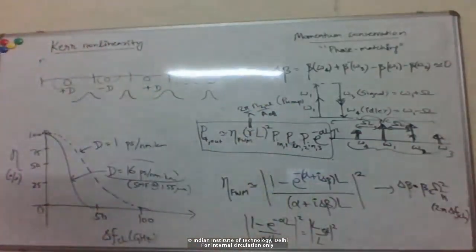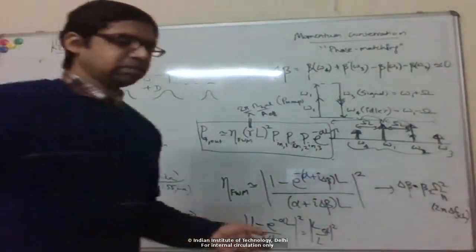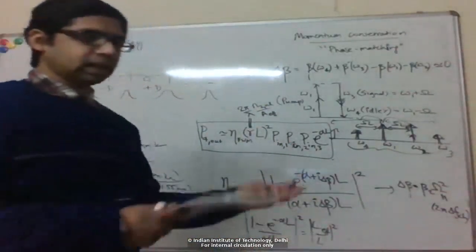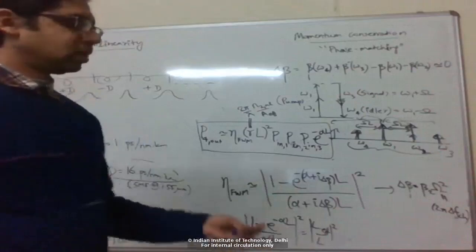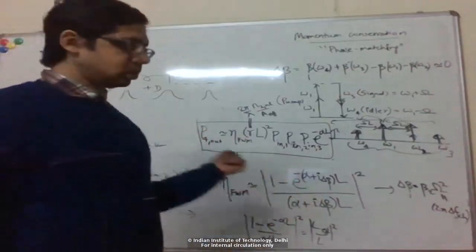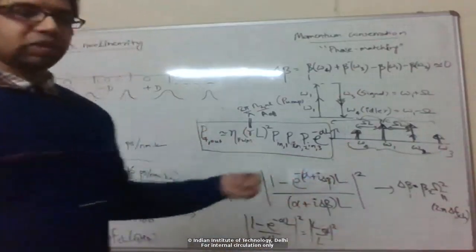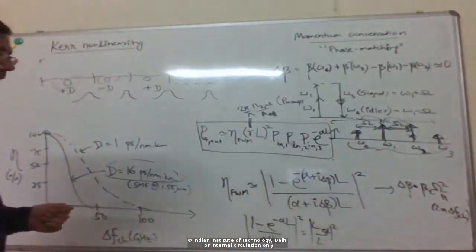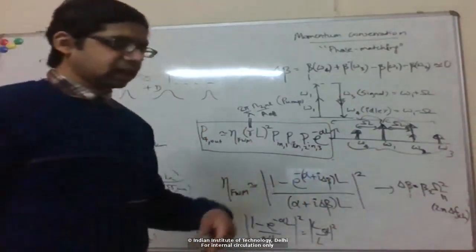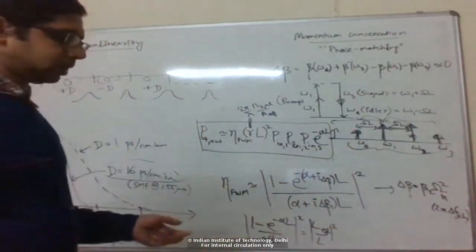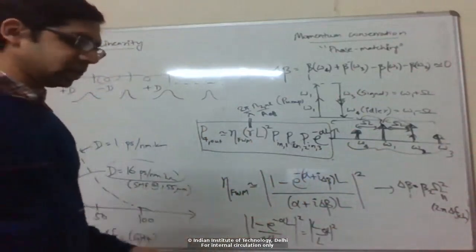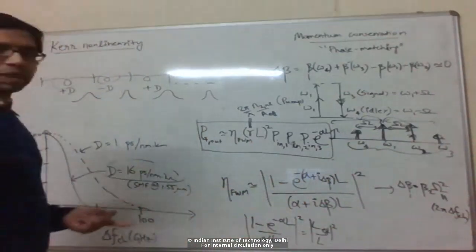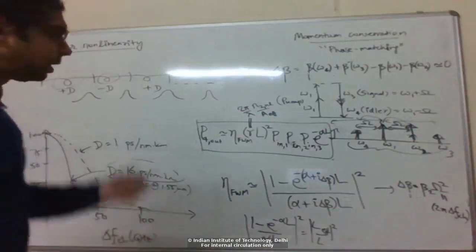Of course you can do it by first detecting the data, converting to electronic form, then remodulating the data with a new laser at the new wavelength. But this optical-to-electrical and electrical-to-optical conversion is limited in speed and adds noise, etc. So if you can do this all optically, it's much better.